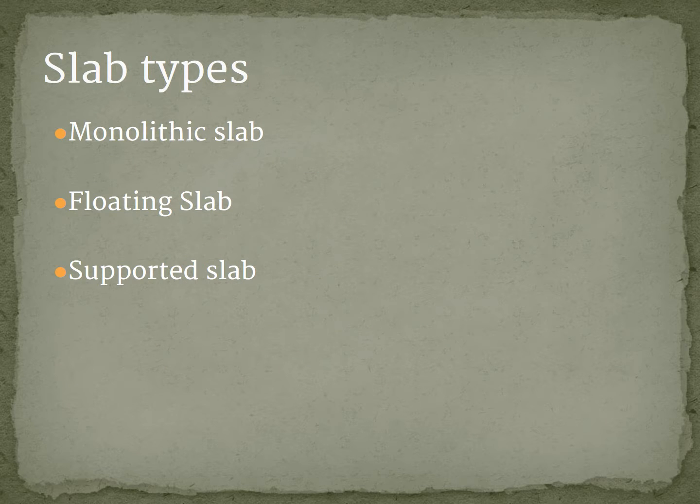To understand calculating the termiticides further, it's really important that you need to know the slab types. Number one, let's look at the monolithic slab. The monolithic slab is going to be a slab that actually is a one-pour slab, so it's not going to have an independent foundation wall or anything like that. The whole house actually sits on this slab. This is a very easy home to treat, because when we're treating this home, we're not really doing any drilling. All we can do is trench and treat in the soil. Now we can down drill the patios and slab porches against the house, but we're not going to do any drilling or treatment on the slab itself.